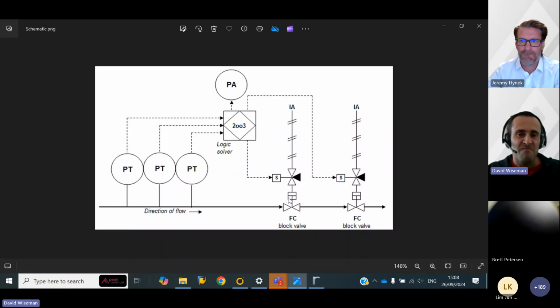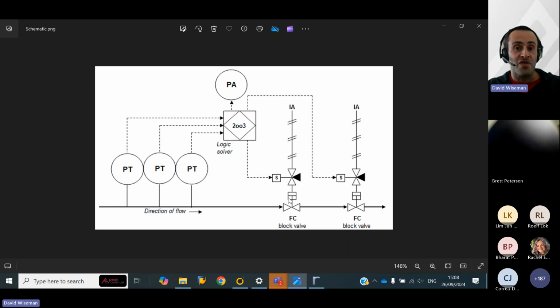But we need to look at a fault tree for this system. And of course, a fault tree is always looking for maybe a failure of that system or a hazardous scenario arising in that system. In our case, it might be a failure to, say, trigger the final elements. The system is no longer going to respond on demand. We're in a dangerous failed state where if an overpressure were to occur, we would not be able to respond to that because some aspect of our system is not working.